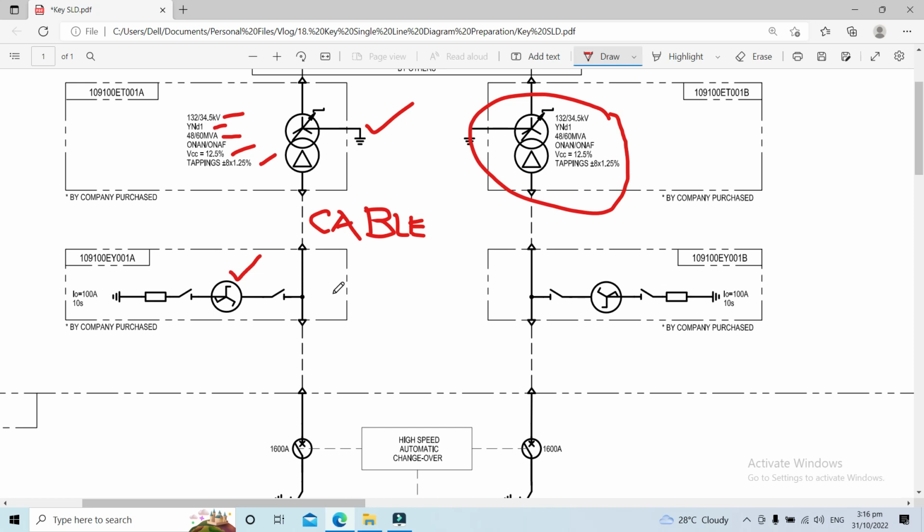The zigzag connection in power systems traps triple harmonics. What are those triple harmonics? 3rd, 9th, and 15th currents. The windings trap the harmonic currents and prevent them from traveling upstream, where they can produce undesirable effects.